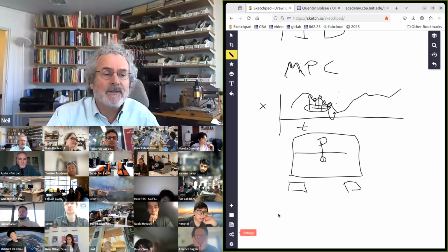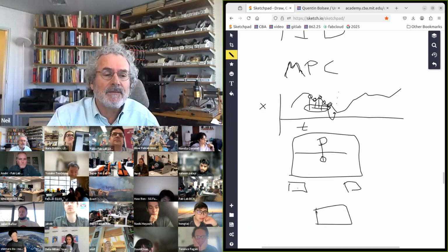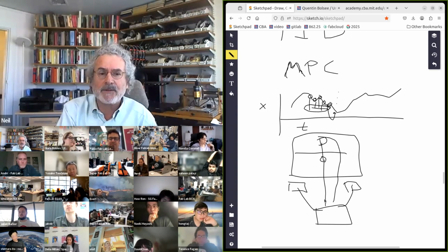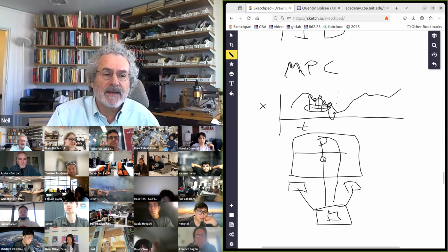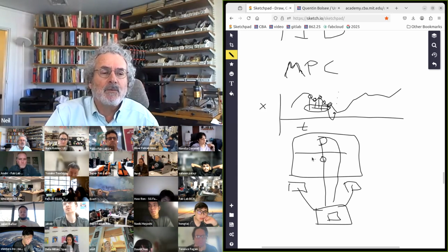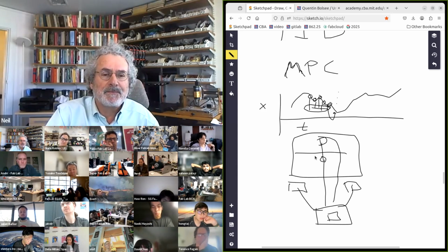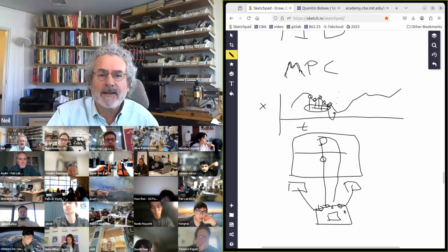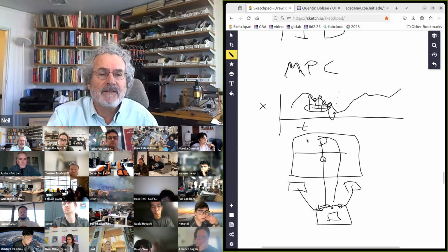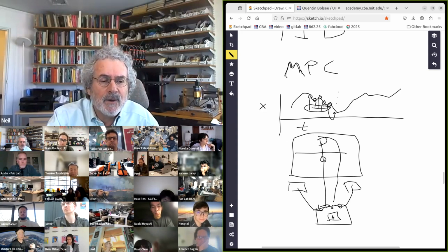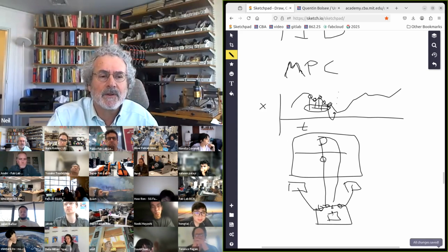The standard way to do it is we send all of these back to a single controller. And I'll show you examples of that. That's easy because this controller can talk to everything. What's bad about this is, let's say you wanted to add one more degree of freedom to the machine. You can't if you run out of ports on the controller. Or let's say if you wanted to change the design of the axis, you have to get back in and change the code in the controller.